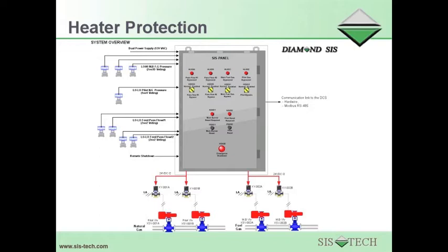the main burner, local and remote heater shutdown commands to trip both pilots and main burners, maintenance bypass key switches for each process variable with local indication, local reset commands to open the pilots and main burner independently, and hardwire or serial communication to the BPCS for alarm indication.